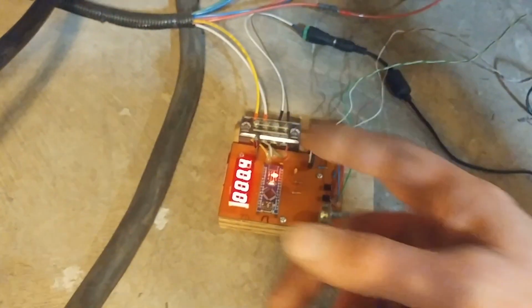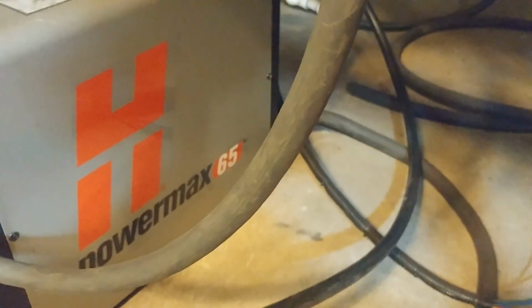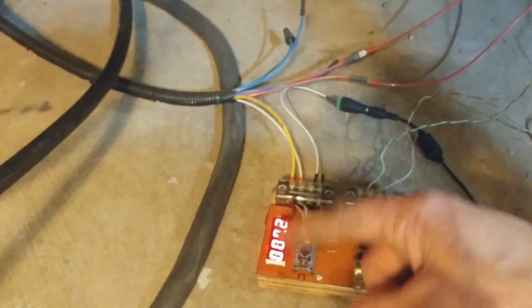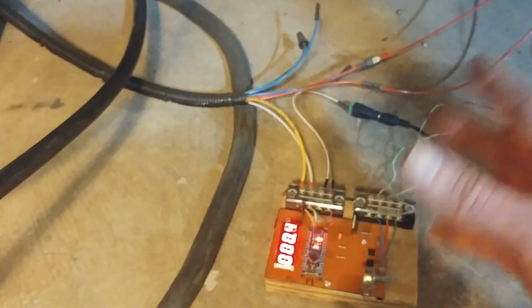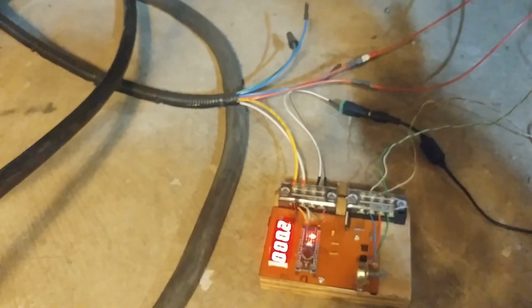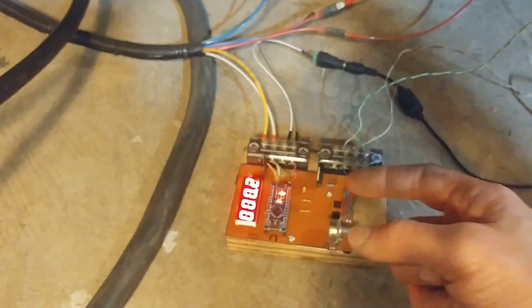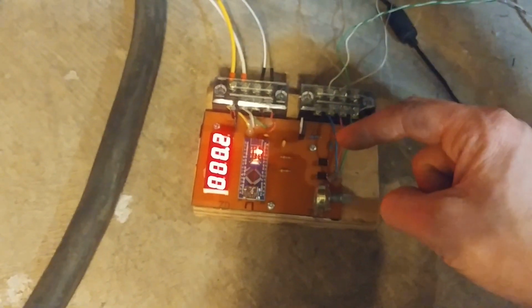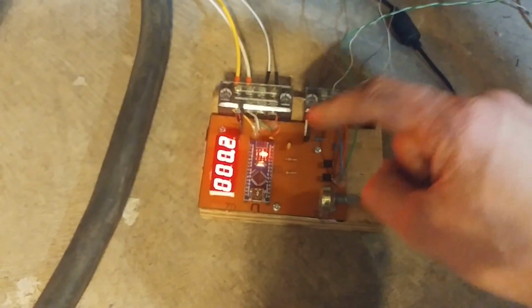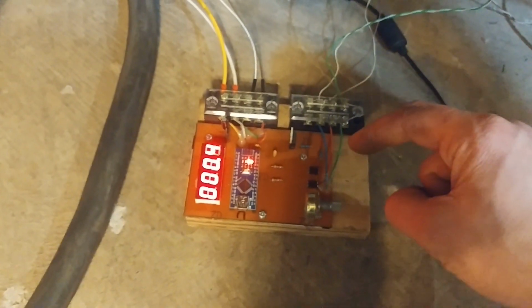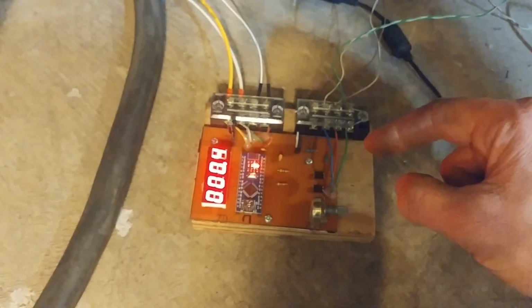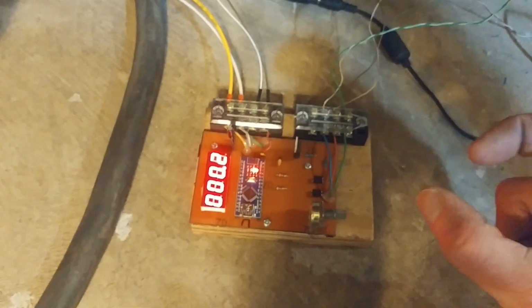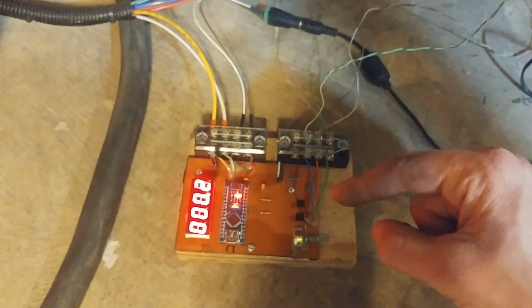And that's important because this is hooked up to a plasma cutter that puts out 300 volts DC. So at some point, you might have a high voltage here that crosses the wire by mistake, and then it can fry your computer. And to keep it from doing that, we have the opto-isolators. And there's a pair of pins on the Arduino that controls this pair of opto-isolators. And basically, when you activate that, it connects the two pins on the right-hand side just using that signal of light. So it kind of acts as a switch on this side here.